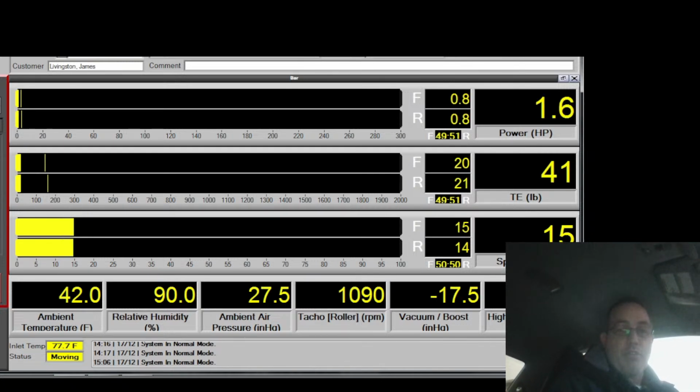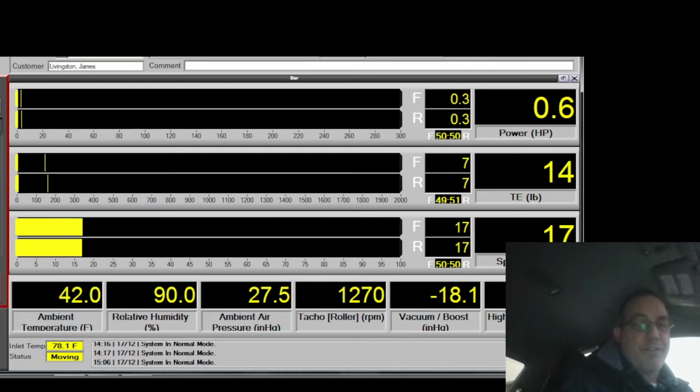It just sucks for the tuner who has to try and figure out what's in the car, because the customer says, oh, I got 1300s in it. Great. Which ones? Are they the ones that flow 1315 or the ones that flow 1350? Is it a 0.93 or a 1.03 millisecond latency at 14 volts? Is it negative 45% or negative 17% at 380 or 400 milliseconds of pulse width? Right? So now it becomes an issue where you're just like, what do I do?